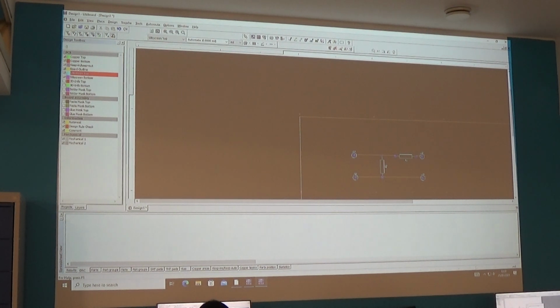So there we are, and that's what's called a rat's nest. If you've ever seen a rat's nest, you probably don't want to see a rat's nest. It's a bloomin' mess in the real world of rats. A rat's nest is just a series of interconnections, but they're not physical, they're virtual. So it's just how the circuit is wired. But your simulator needs to know what the rat's nest is before it can make the copper interconnects.